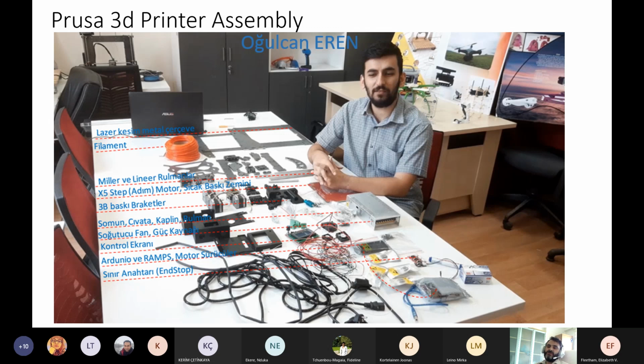The fact that you can produce your CAD design quickly and easily in a computer environment on this FDM 3D printer is actually due to the machine's ability to melt the material and place it at very precise positions. So this is called additive manufacturing. In a 3D printer, there are parts such as motors that position the printhead, plastic used for the model, and an extrusion head to melt the plastic and place it onto a table positioned in the horizontal plane.